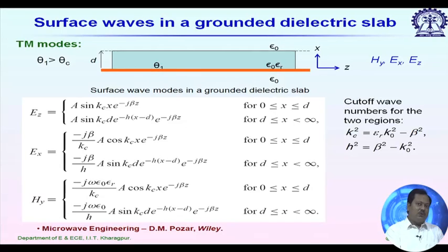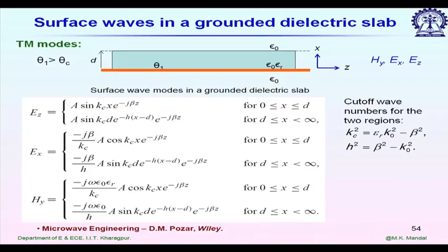as well as TM modes. So, we will see TE and TM, again we have TE0 and TM0 modes, and these two modes do not have any cutoff frequency, and it creates a lot of problems for any printed circuit board lines. For example, if we fabricate a microstrip line or a coplanar waveguide in any printed circuit board technology. So, microstrip, we have a strip over a dielectric slab and below we have ground. So, we will be facing a similar problem just like what we are going to discuss here.